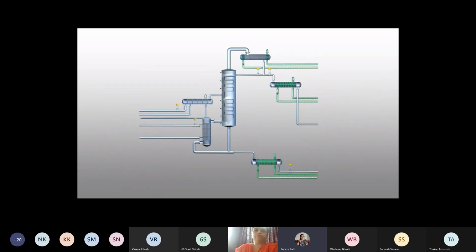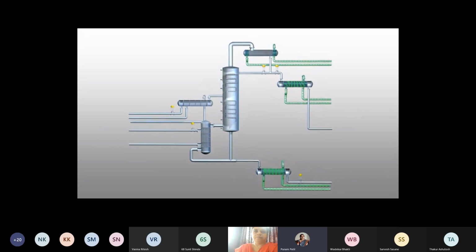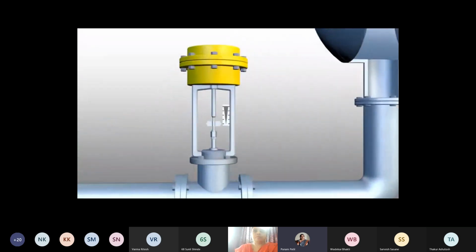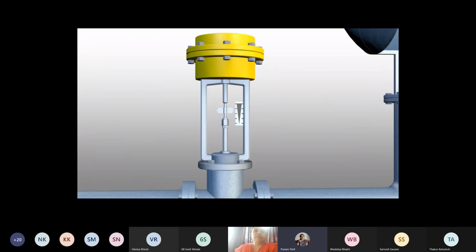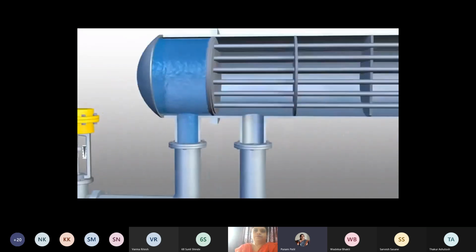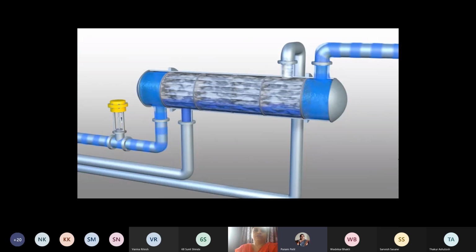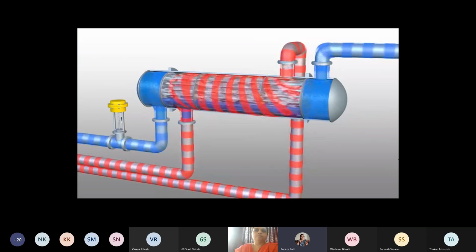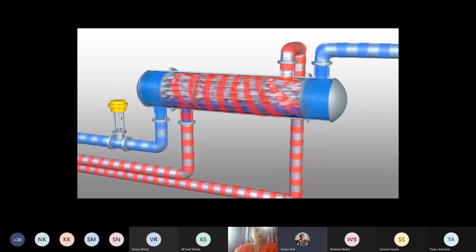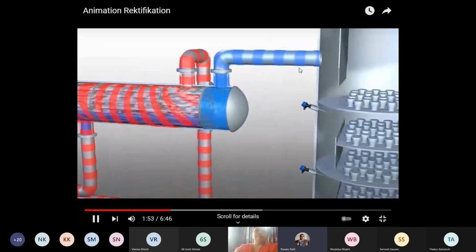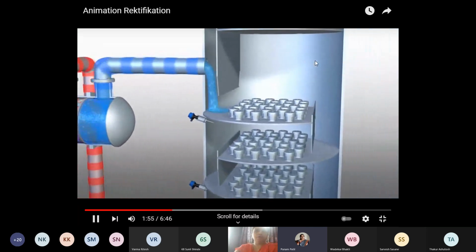When the feed valve is open, feed is added to the preheater, that we will see. Now the feed valve is closed. When it is open, feed flow starts, and feed is added into the preheater, where hot utility is provided to increase the temperature. Okay, so the feed is heated. That feed is added to the distillation column.